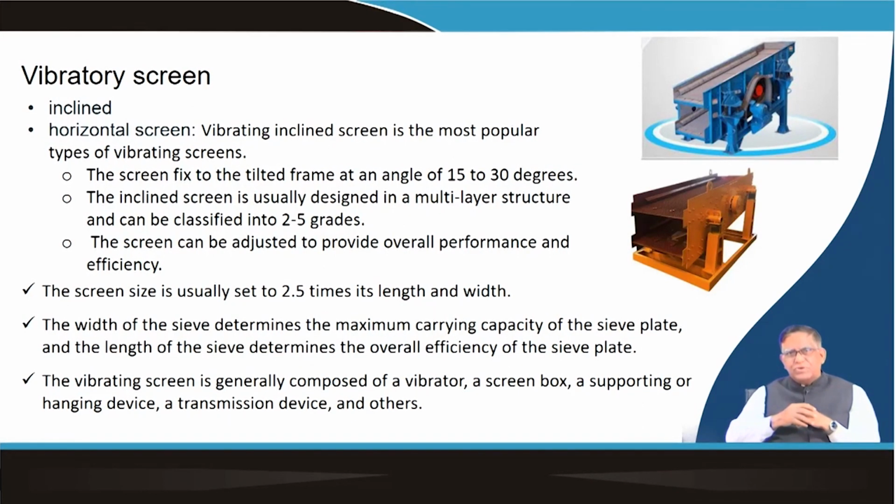That one thing will be important for knowing, to become a maintenance engineer, or if you want to improve the performance of this in the field, how the vibration is given. The vibrations can be given by different methods. One, you can have an eccentric shaft giving the vibration, or you may have a spring on which this is moving, and with a spring you can allow the vibrations, or the drive itself in the motor, there will be vibrations coming.